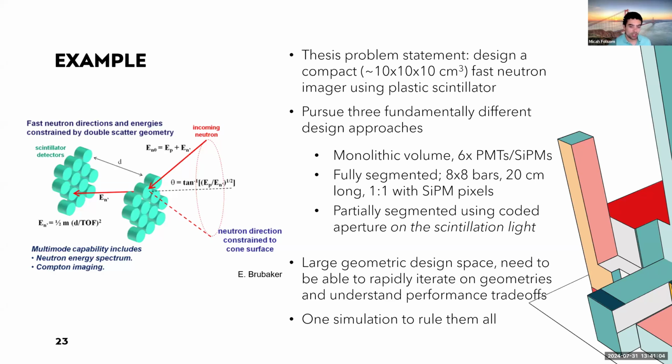And so what we wanted was one Geant4 simulation where we could do these very different designs, maybe the same photodetectors, the same SiPMs or multi-unit PMTs, but the volume's chopped up differently. Maybe you have some different reflectors and things in there. And we want to be able to enter one command and flip between the geometries and then define the same sources, the same everything, and then we're all sharing the benefits of the same code.